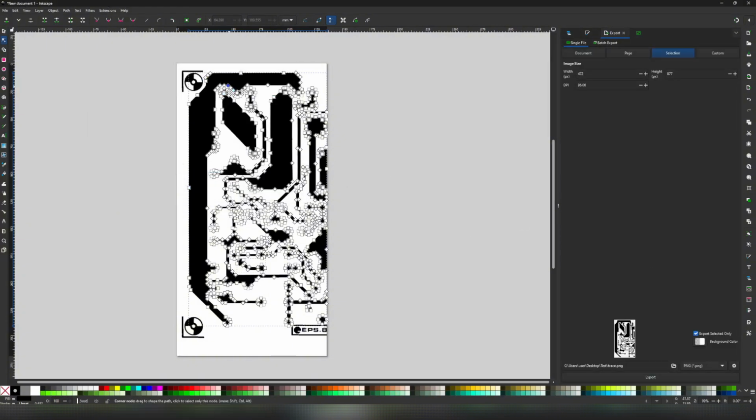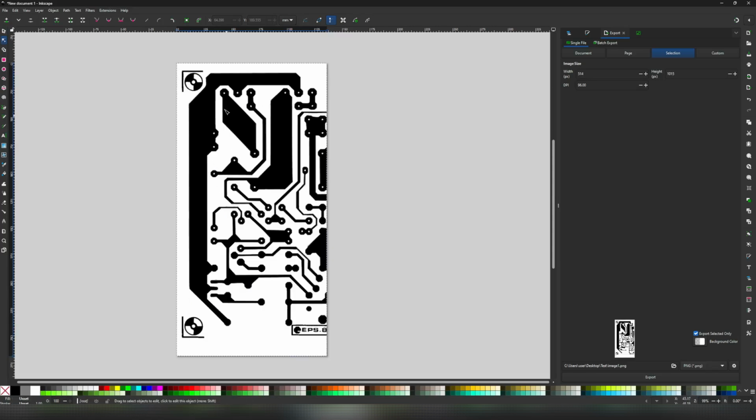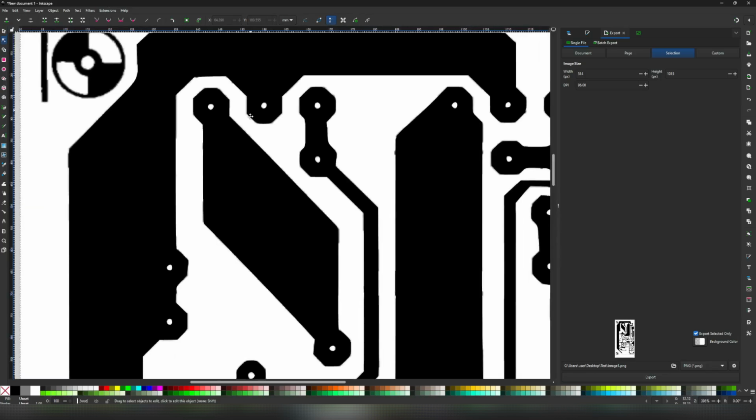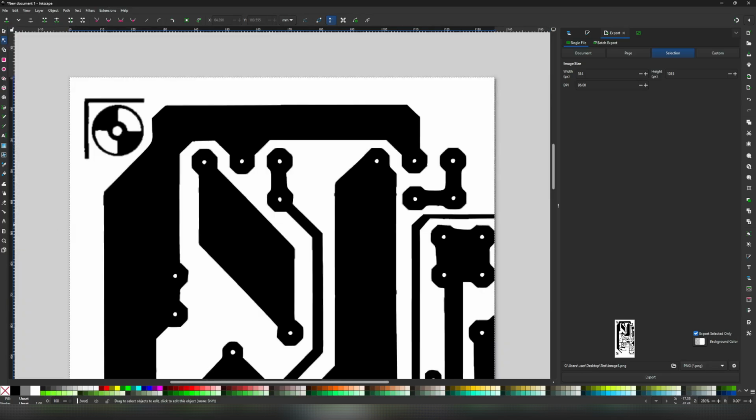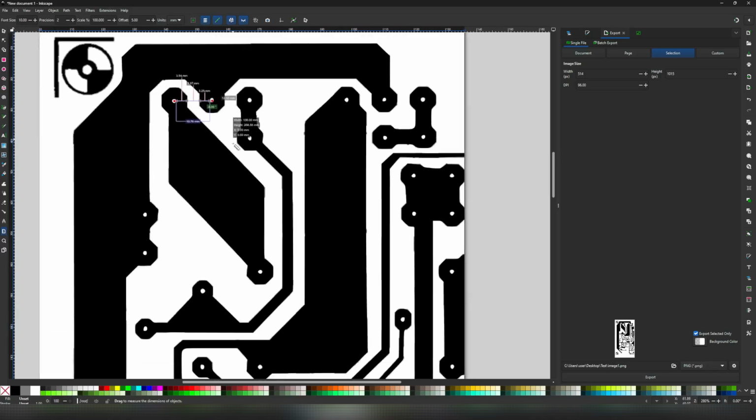One thing that's important is if your board has to have physical dimensions. So let's say the distance between these holes should be a certain quantity, like, for the sake of this exercise, 5 millimeters. You can just select the measure tool here, hold Control and start dragging from here. This will measure the distance. As you can see now, this is 10.76 millimeters, which is larger than the 5 millimeters I said.